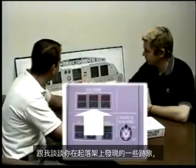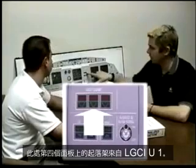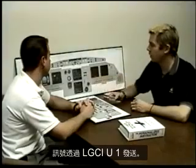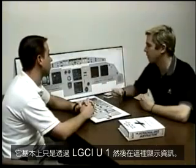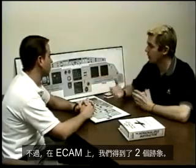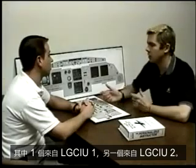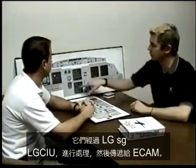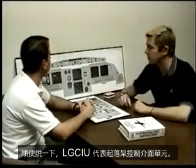Landing gear panel. Talk to me about some of these indications that you find on the landing gear and where they are coming from. Okay, the landing gear indication on the forward panel right here is coming from LGCIU-1. The signal is sent up through LGCIU-1, which doesn't really process it. It just passes through LGCIU-1 and then displays information here. On the ECAM, though, we've got two indications. One comes from LGCIU-1, the other from LGCIU-2. They're independent. They go through the LGCIUs, are processed, and then passed on to the ECAM. LGCIU, by the way, stands for Landing Gear Control Interface Unit.